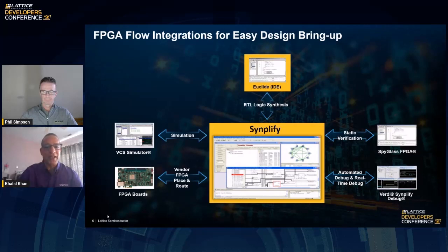SpyGlass provides static verification with RTL-level lint checks and clock domain and reset domain crossing violation checks. Verdi's companion, Euclide, is a comprehensive RTL IDE environment that provides on-the-fly language syntax and language rule checks. It also provides auto-completion and auto-insertion of RTL blocks for simulation and verification flows.